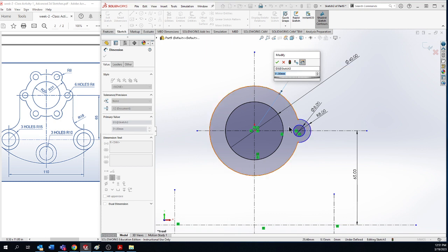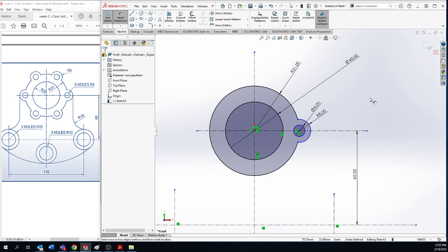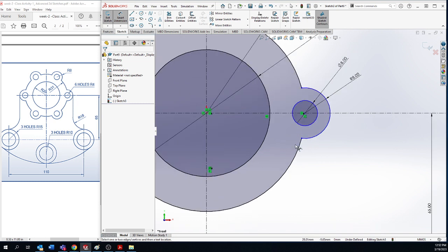So once you remove this element, the outer circle is converted into an arc. When you have an arc, the dimension will be given in terms of radius. By default it is showing 31, since it is given 62 as diameter. Tick OK.